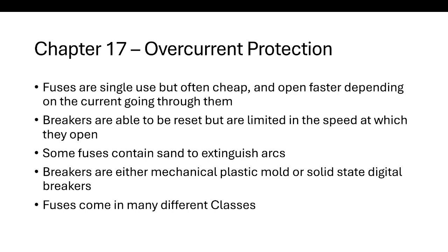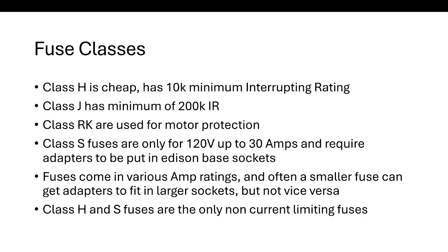Some fuses contain sand to extinguish the arcs that happen in them. Breakers are usually mechanical plastic molded breakers like you would see in a house, but now there are solid state digital breakers as well, which I believe act faster and just have fewer moving parts. And fuses come in a lot of different classes, which I go over here.